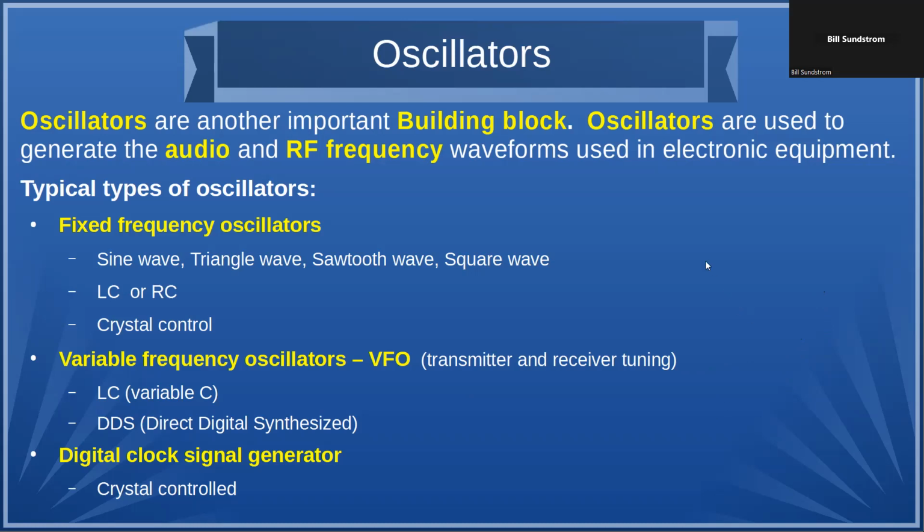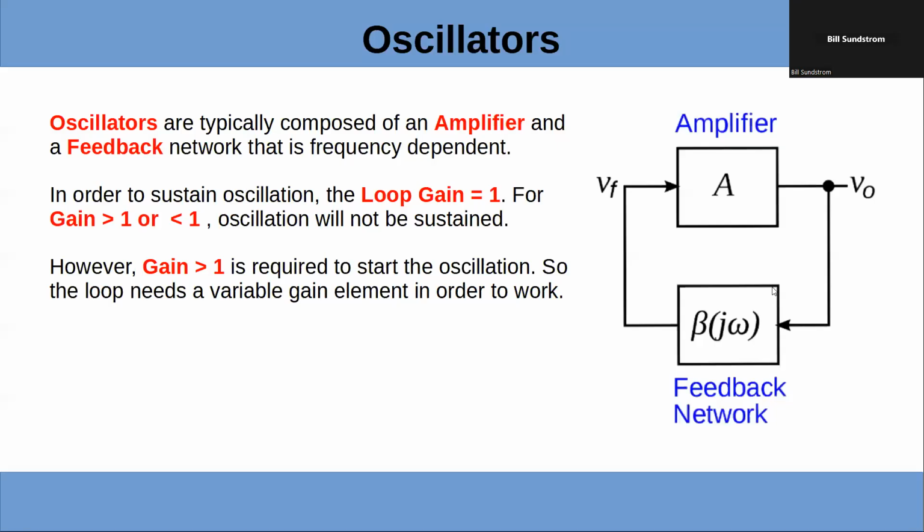They're usually all run off of one or more clock signals, a timing signal as a reference. And that's usually done with a crystal controlled fixed oscillator. They actually sell them in small packages where you just apply a voltage and you get a square wave clock signal out of it.